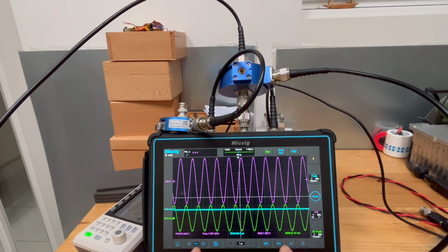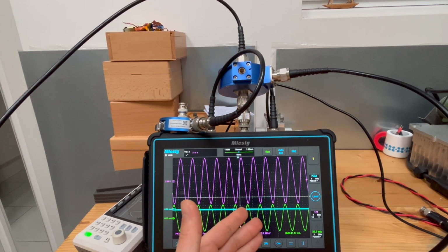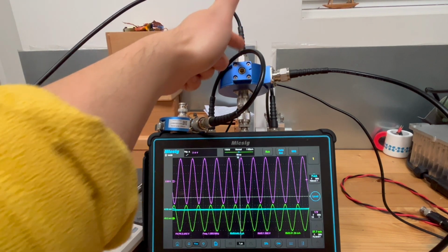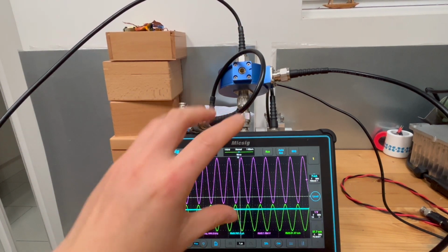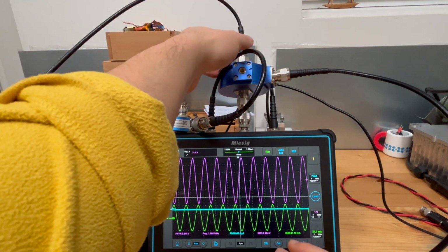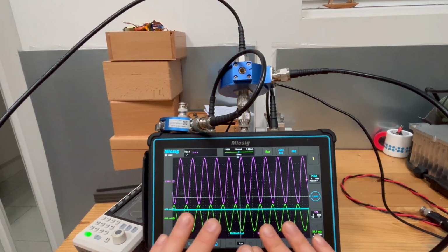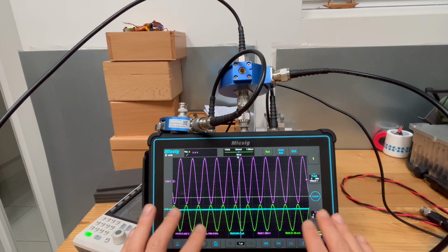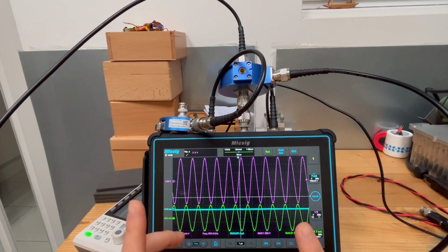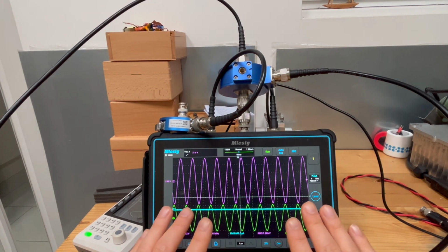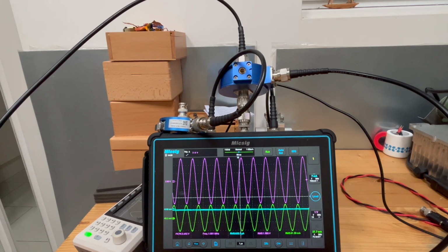Also, if you remember, just before this test, at 100 kilohertz, my waveform of current and voltage had a phase shift, whereas now it's pretty much in phase. I mean, the polarity is different because this probe has a direction feature. If I connect this current probe the other way around, this would match. But if you look at the waveform at 100 kilohertz, you find there is an inductive lag there, right?